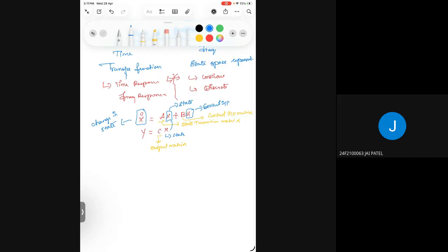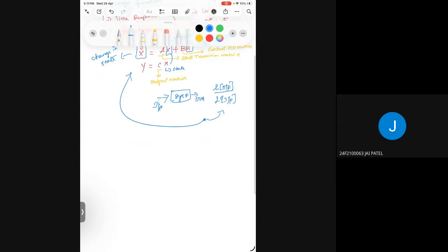of a system. So in transfer function, it will be Laplace of output by Laplace of input, where here it will tell a relationship between an input to the system, so what output it is giving. This is one form of representation. This is another form of representation representing the same system. You can represent the same RLC circuit in either transfer function or state space form. Same RC circuit or any mass spring damper system in state space form and the transfer function form.